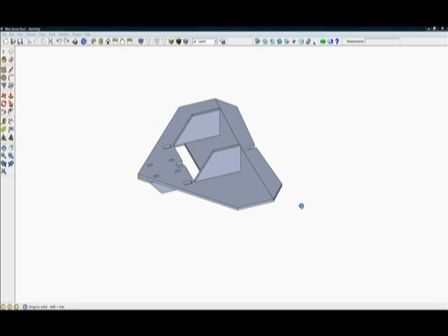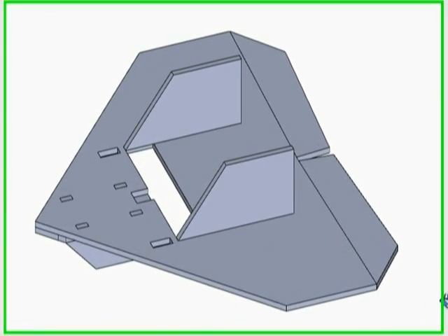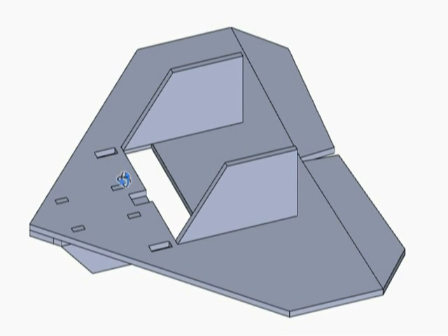All right, with every new model that we've worked up, before we can start laying out parts and cutting our parts out and so forth, we have to know a couple of things. We have to know what foam we're using. Of course, by the time we have developed our three-dimensional model, we know what foam we're using. Are we using 6mm EPP? Are we using 6mm Depron? Are we using roughly 6 millimeter, say 1/4 inch fan fold foam? You want to already know that so that you can get your tabs and slots and everything correct at that point. But now it's time to look at a few other things.